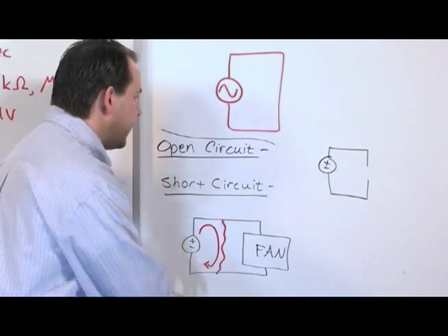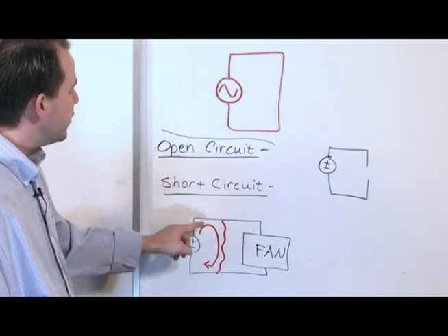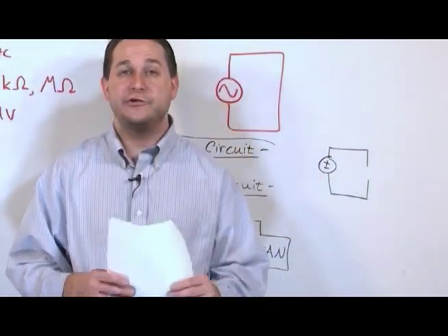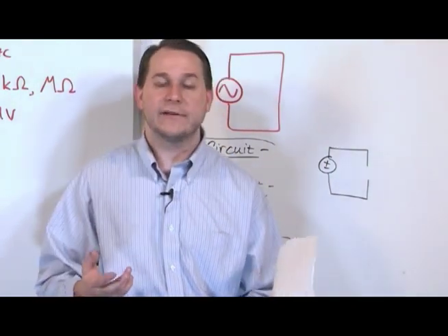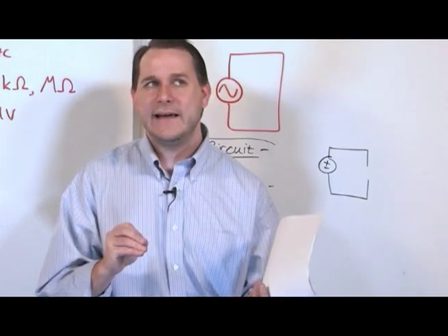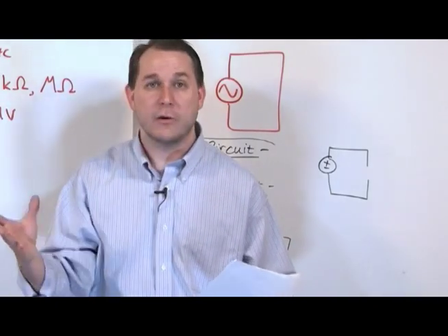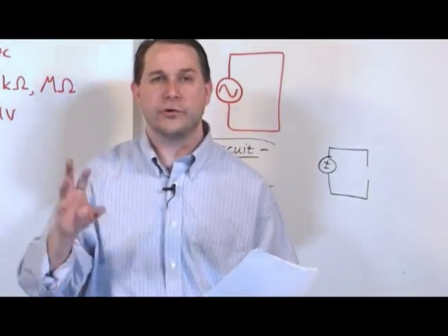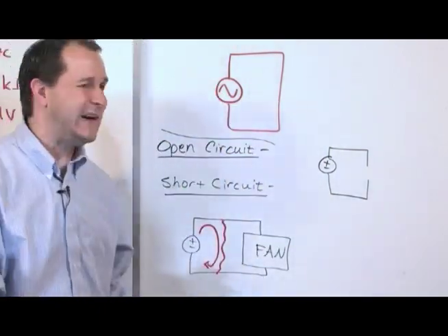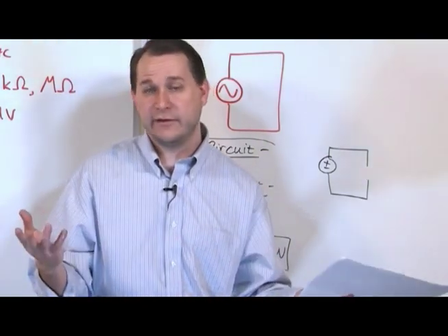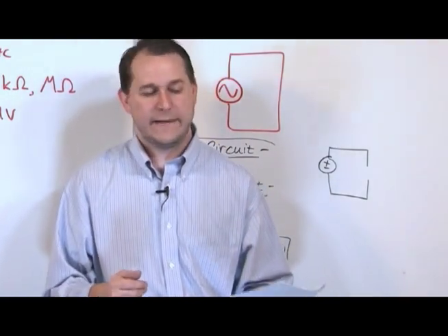And it's very bad for lots of reasons, but because whenever you start to get current going through a wire like this with no resistance or very low resistance, you can actually generate a lot of heat, and you can actually cause a fire. And that's why you have those circuit breakers outside of your home. Those are there to detect if any short circuits happen, to detect the extra current, the increased current that comes from it, and to shut them off. If you get any kind of a short circuit in your washer or your dryer, maybe some wires start to touch, the current is going to start to go up really, really fast through this tiny little leg, and your circuit breaker is in the circuit with that. It detects that, and then it shuts the circuit down. So that's basically how that works.